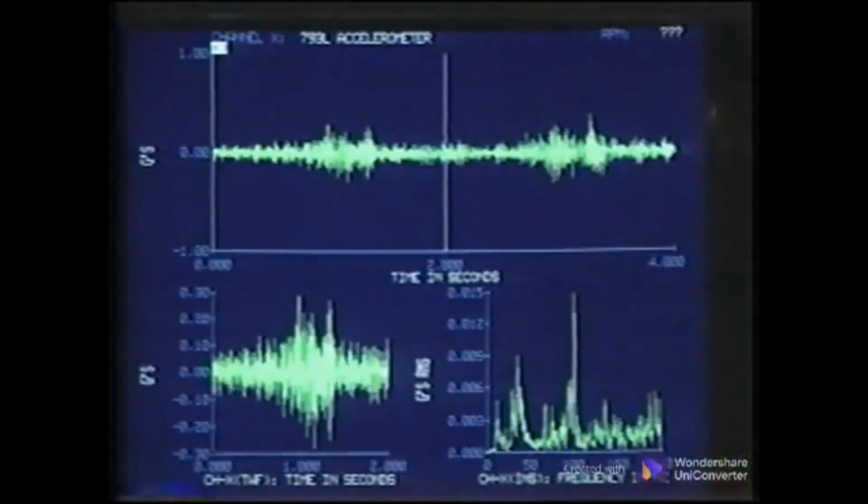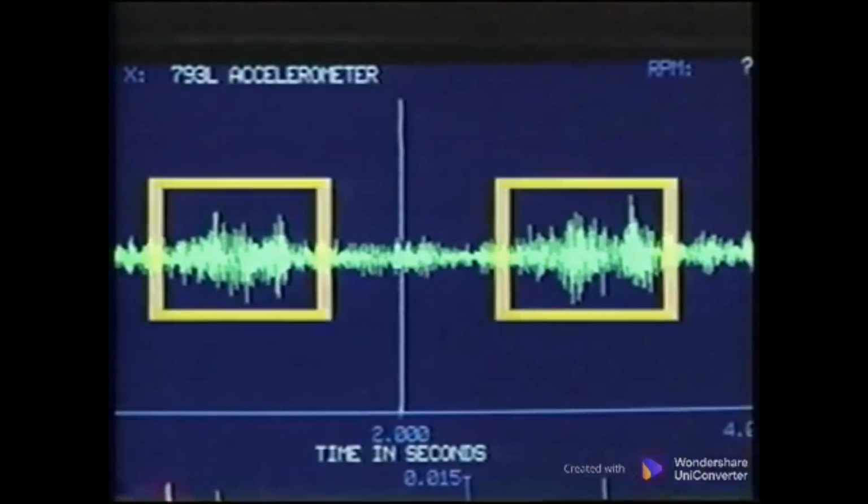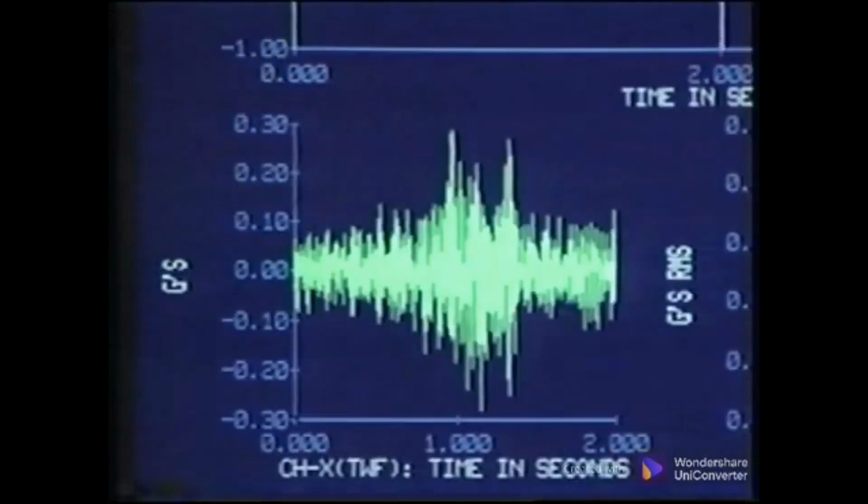For very slow-speed machinery, that is, below 200 RPM shaft speeds, time waveforms may need to be as long as 1 minute to capture transient or very low-frequency events. This data is over a 4-second period. The event occurred once every 2 seconds with a half-second duration. The problem in the machine would have been more difficult to find and diagnose without a long time span in the waveform.